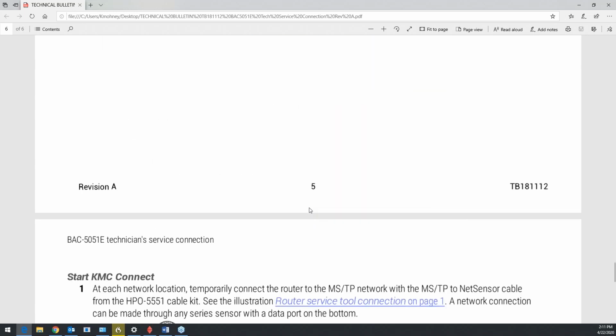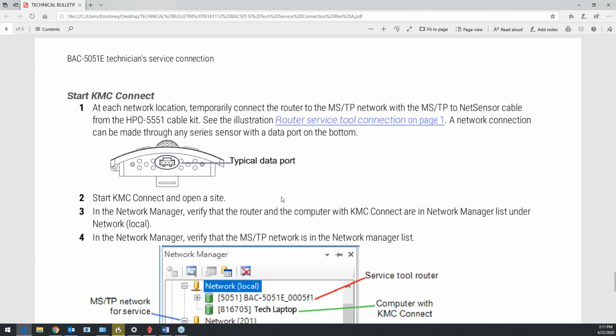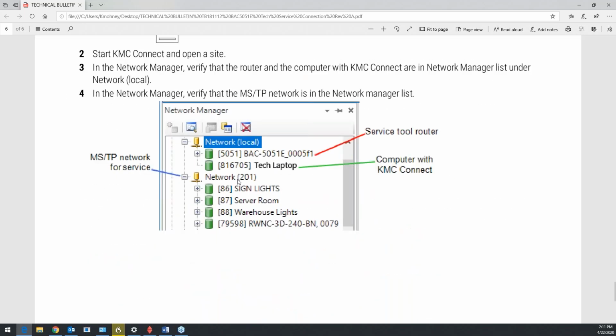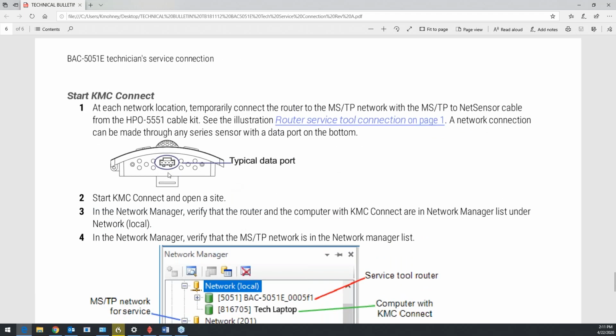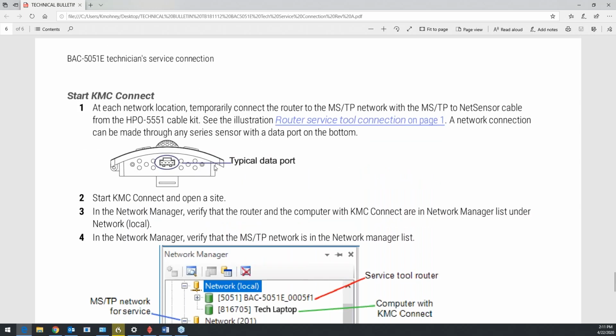So you can go out, walk around the building and plug into this port on the bottom of a net sensor and not mess up your network, not get a bunch of duplicate networks. If you don't use Learn Networks, then you're going to get duplicate networks, because that controller is going to be on two networks. So you've got to use that Learn Networks.